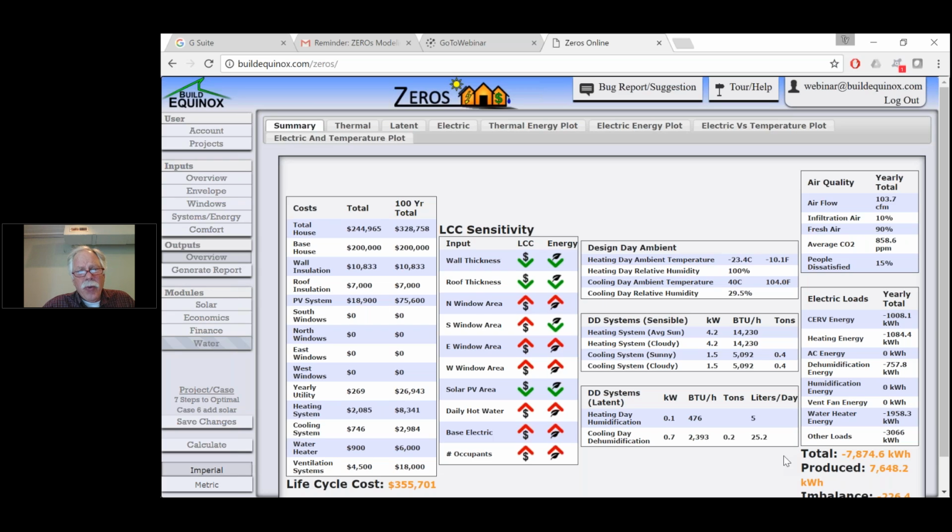So a 6,000 watt system would produce maybe 6,000 kilowatt hours. And if you're more like, say, Phoenix or the southern US, that number might be about 1.4. So 6,000 watt system might give you a little over 8,000 kilowatt hours. And so when you see this number, just put in something near that number for the solar wattage.